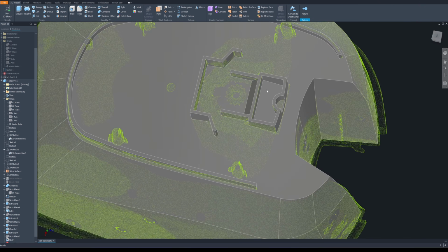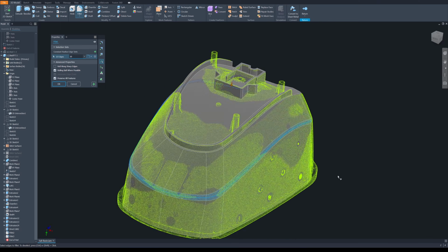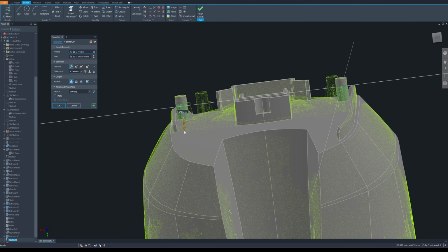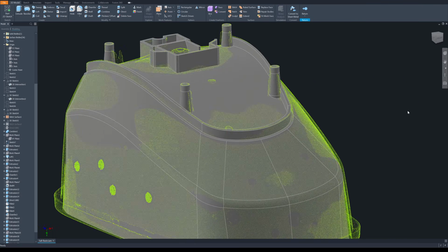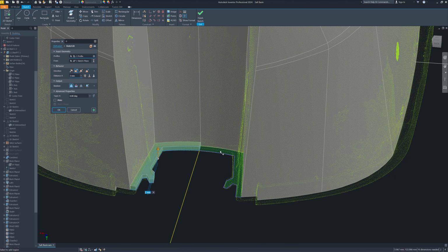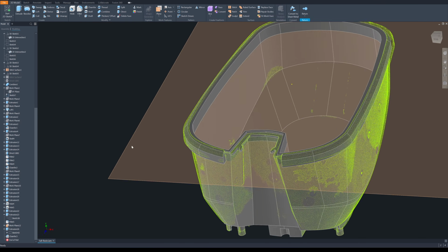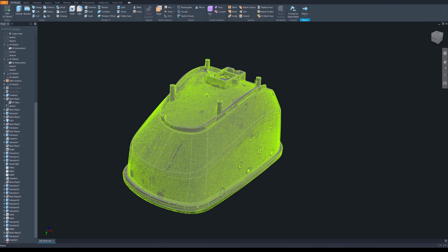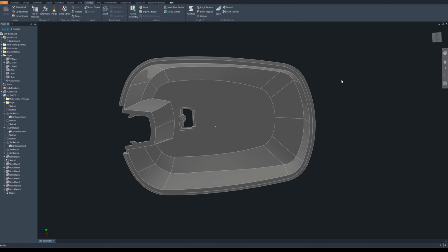Okay, next I'm going to make an opening here. Let me cut this through. Next I'm going to do a fillet around the edge here for 10mm. Now I'm making an extrusion for the fixing point. I'm going to neglect the stiffener because it will be more difficult to print. And then I make an extrusion for the clips. And then I make a simple extrusion for the edge stiffener. Okay, here's the finished model ready for printing.